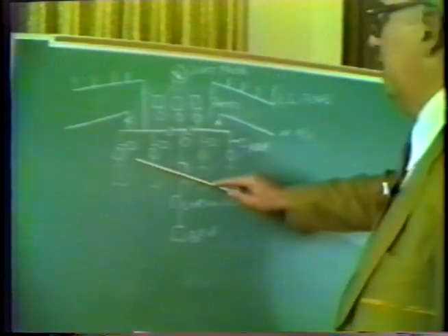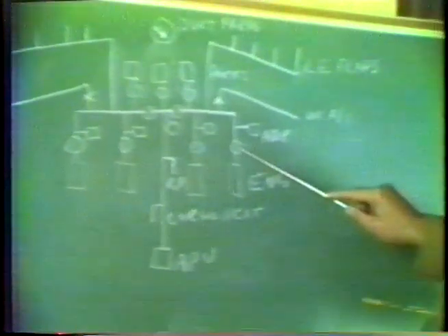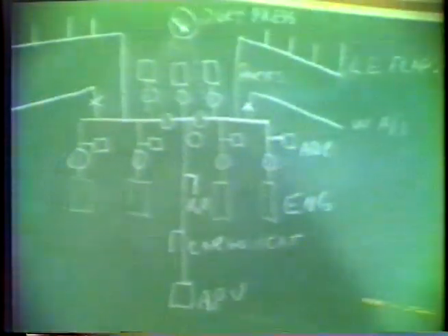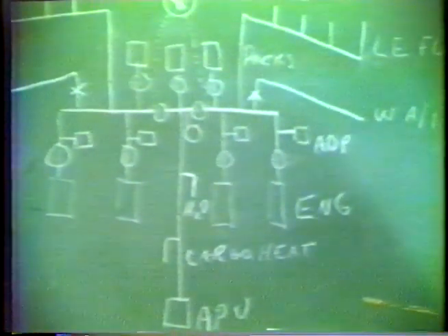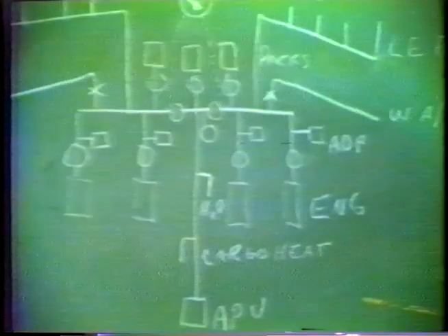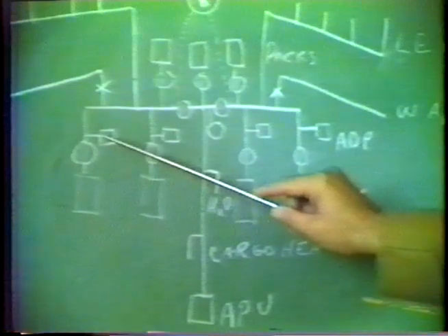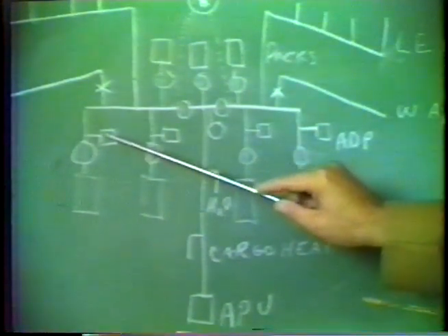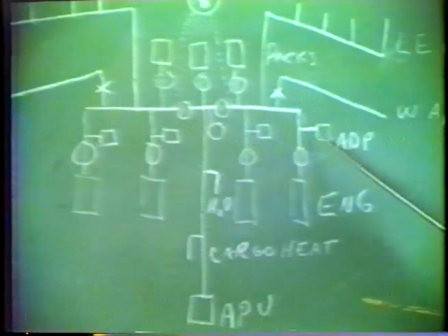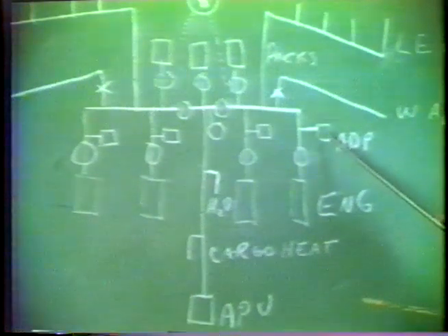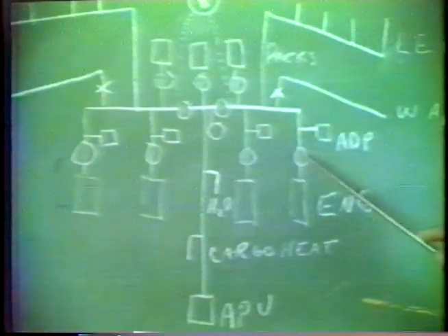The air coming out of the engines is controlled by 4 bleed valves. Now the bleed valves have a simple control knob on the panel. However, they are not simple devices. They have a great deal of automatic control functions to them. Directly downstream of the control valve, there are 4 air-driven pumps, and it taps the air in the pylon downstream of the bleed valve.